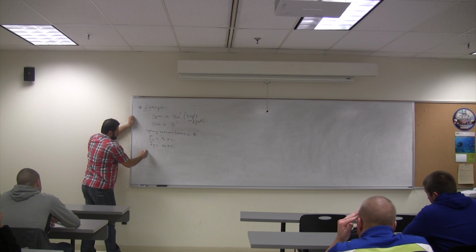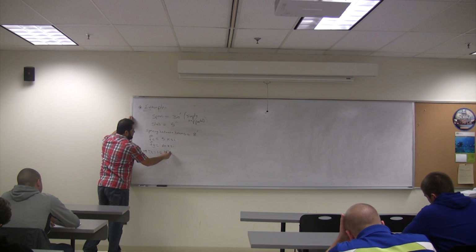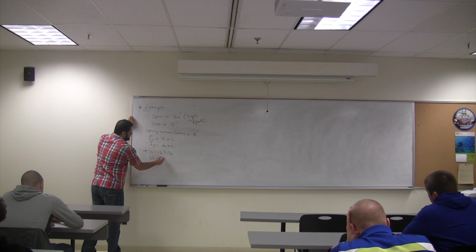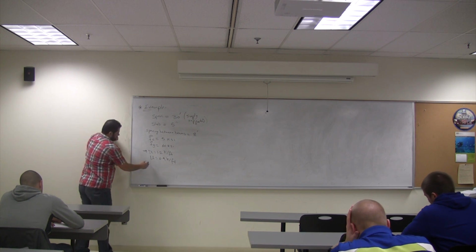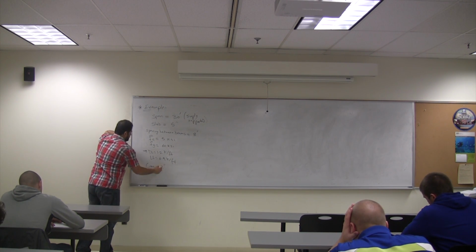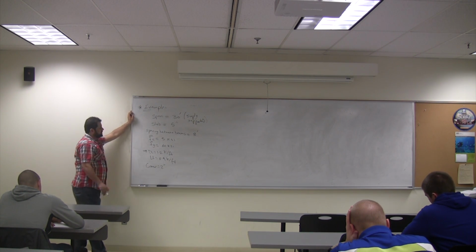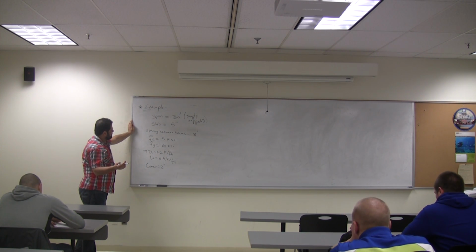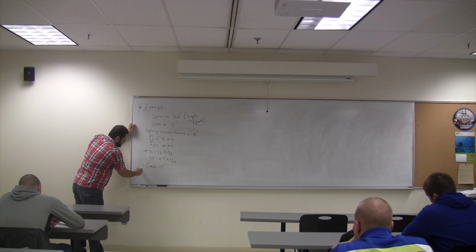Dead load 1.2 kip per foot. Live load 0.9 kip per foot. Service. Cover 2 inch. Normal weight concrete, non-epoxy coated steel. All of these, whenever you need them, we'll assume them. Anything else? Any information that we need, we will assume.